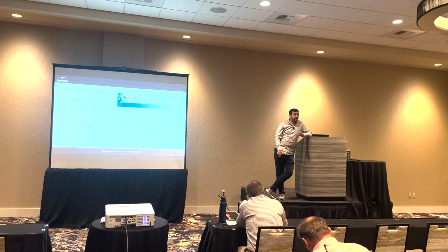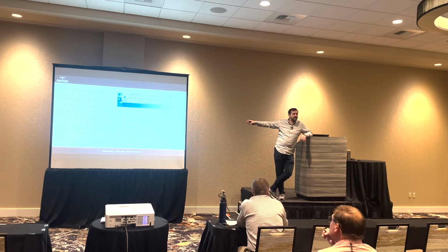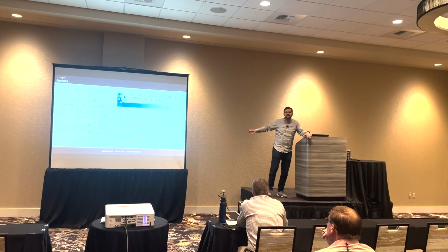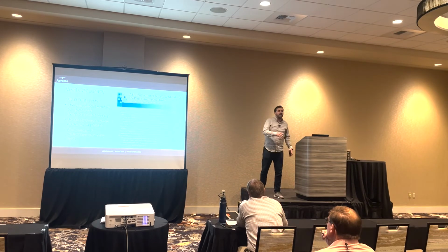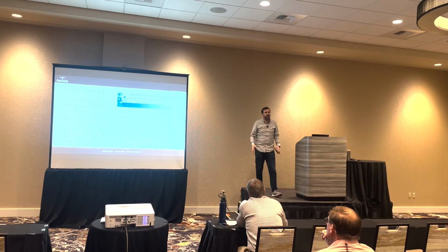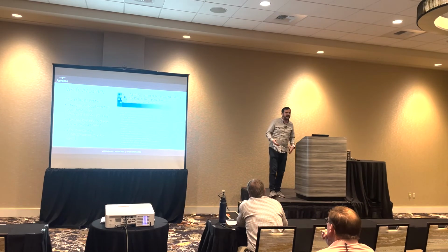Yes, absolutely. And if you really want to read about it, this is the gold standard document for measuring that. In verifying accuracy, the accuracy statements in this document say we have tested the accuracy compared to GPS, compared to total station data, compared to whatever, and found the average deviation to be 4/1000ths of a foot with a 95% confidence interval of 9/1000ths of a foot, something like that. It actually tells you exactly what your accuracy can be.